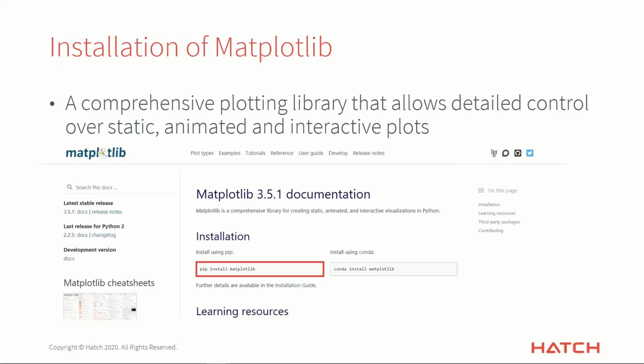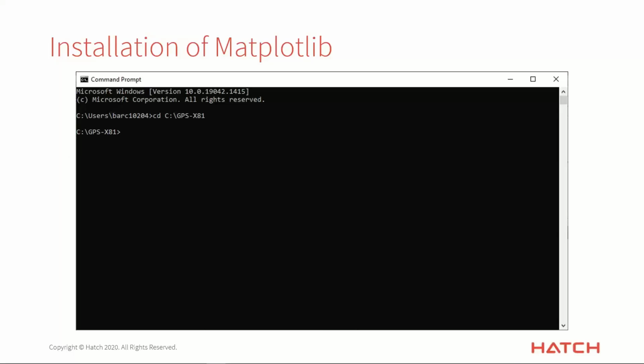So if you actually want to go about installing this library in GPSX, the very first thing you need to do is open your command prompt and navigate to the GPSX folder on your machine. Where for me, that's just directly on my C drive in GPSX 8.1.